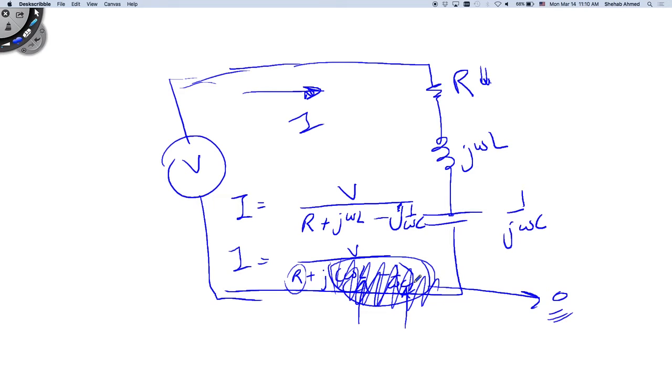Mechanical systems, same thing. Motors with shafts that rotate have a resonant frequency. A shaft will rotate at a certain speed. You never want to rotate the shaft at its resonant frequency, because if you do, it will vibrate and you will not be able to control it anymore.